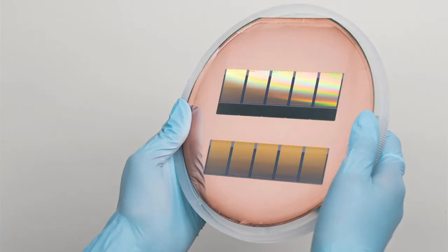At Neuralink, we have an incredible team that's been tackling these challenges and have been able to make high channel count polymer probes. And this image is a silicon wafer that holds 10 of these polymer arrays. In this design, each of those arrays has over 3,000 channels. So what that means is in this one wafer, we've manufactured over 30,000 electrodes and over 30,000 insulated wires. This is something that can't be done with the way current medical devices are being made. That rainbow effect is caused by the small feature sizes on these devices that are interacting with the nanometer size wavelengths of light that are reflecting off of them.